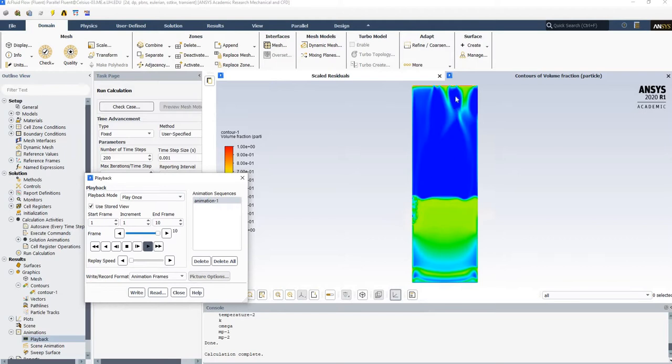It can happen due to the fluid flow pushing those very small particles near the outlet. Other times, even when I reduced the velocity, it was still stuck in a small layer. So I'm not very sure about that, but usually it should not happen. Sometimes it happens, so just rerun that.